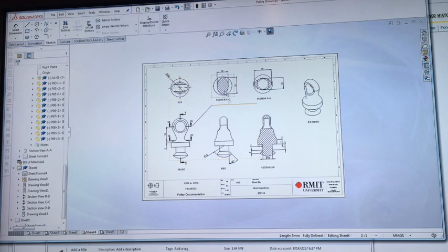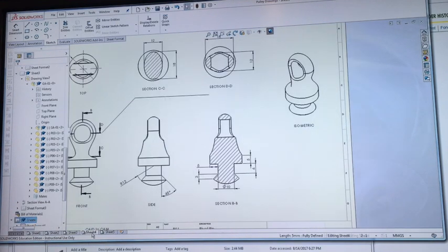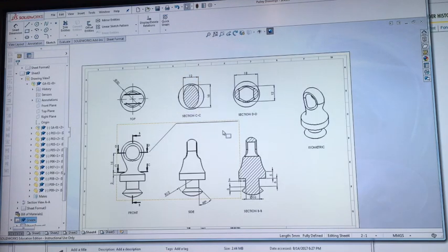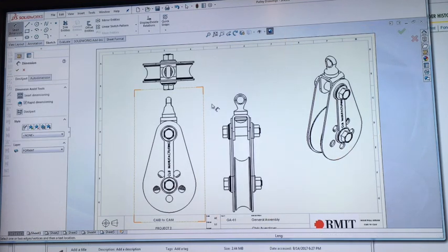So every view that you have in your drawings requires a view label saying what it is, either a section or section and detail views will be automatic. The other ones, you'll have to put them in manually. And then with dimensioning, okay, for each of your parts, you're dimensioning all the details they're required to measure or check the part. With the assemblies, it's a bit different. On your general assembly page, we're only going to go with 3 dimensions, basically a length, height, and width.